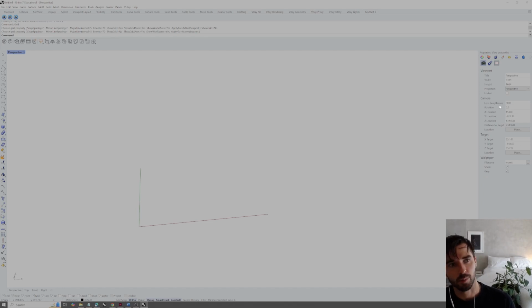So when I was doing the pivot, if I do it here while we're looking at this, we can see that pivot makes the camera location not move, but the target information is what moves. So you see that target information updating, whereas if I just right click and drag to orbit, then my actual camera location is moving, not the target, right?